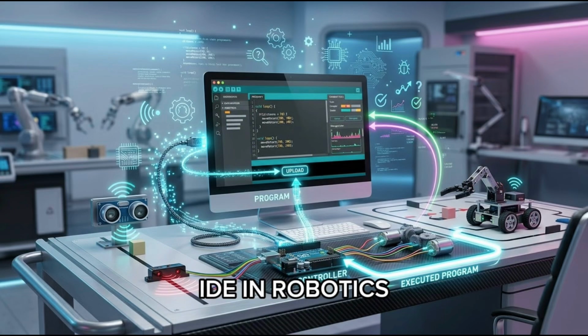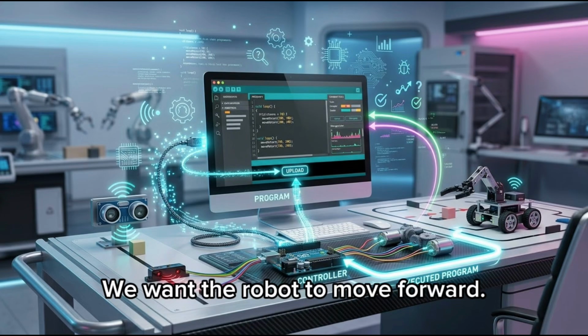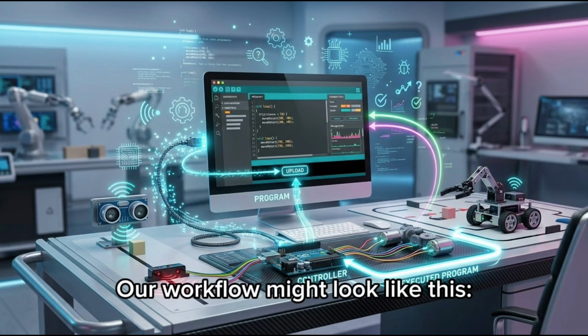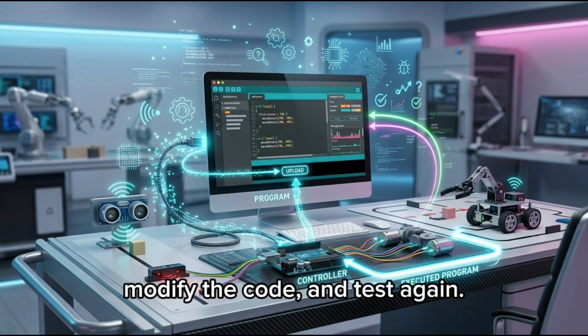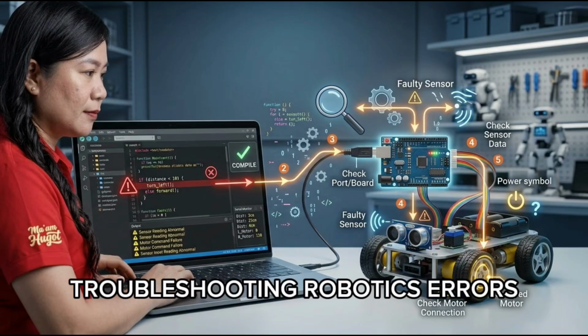IDE in robotics. Let's imagine that we are programming a simple robot. We want the robot to move forward. If its sensor detects an obstacle, it should stop. Our workflow might look like this. Write the code, check for errors, compile the program, upload it to the controller, then test the robot. If the robot doesn't behave as expected, we go back to the IDE, modify the code, and test again. This process is called debugging.